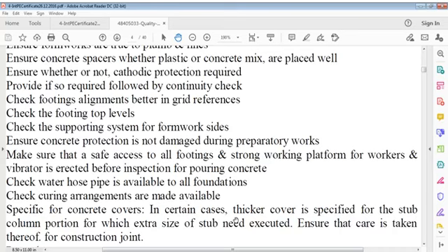So this is specific point of corrosion protection, which is generally taken in plants because corrosion is not acceptable. But here people do not think about this at all, and they put steel parts in water itself. I'm sorry to say that. So cathodic protection is very important item. And if you are going to use epoxy coated bars, so there is no question of corrosion. But remember, in epoxy coated bars, corrosion cannot be controlled. You cannot apply cathodic protection. So where you are going to use protection in your work building.